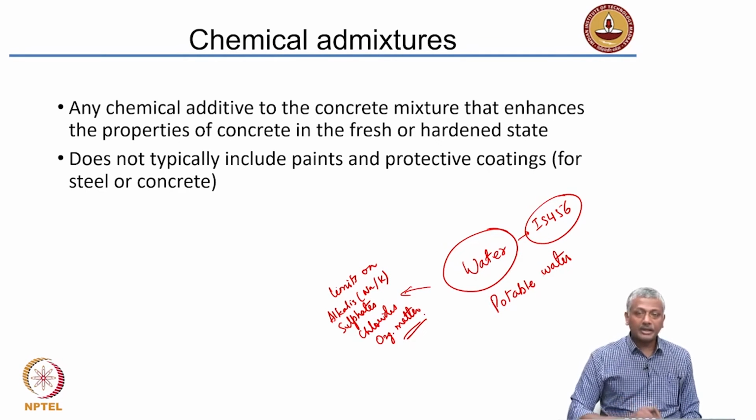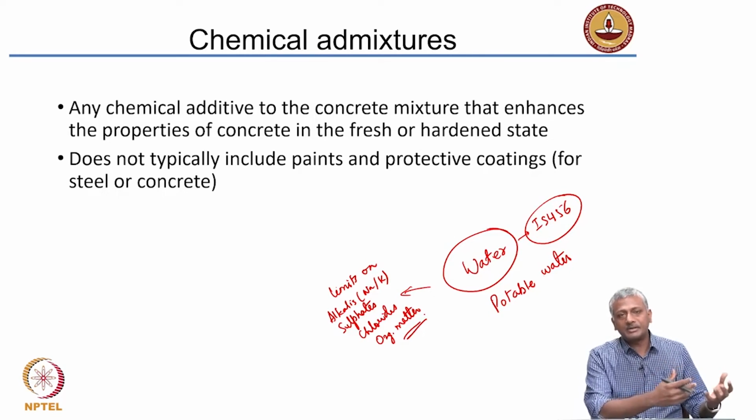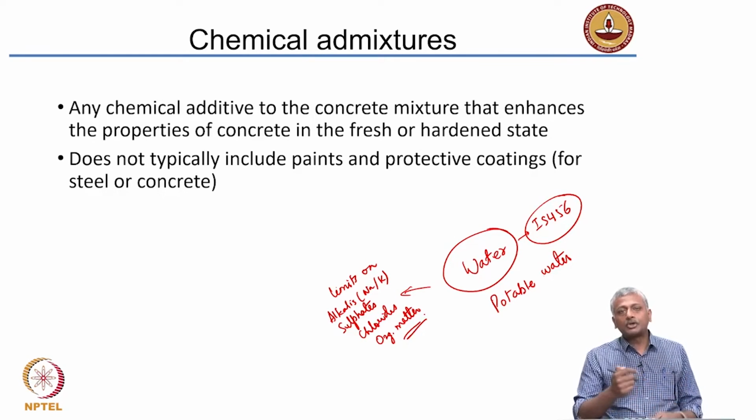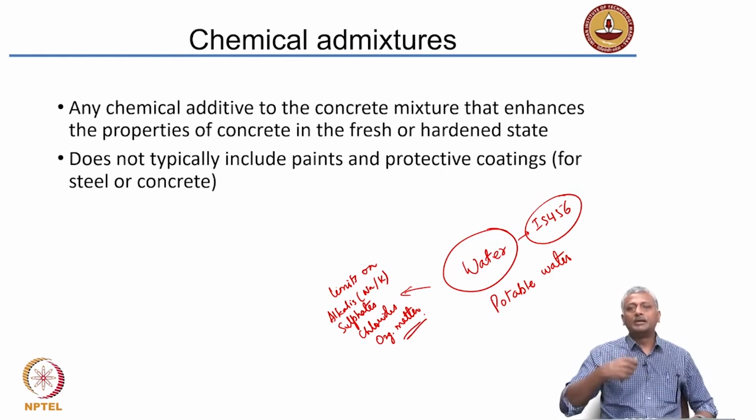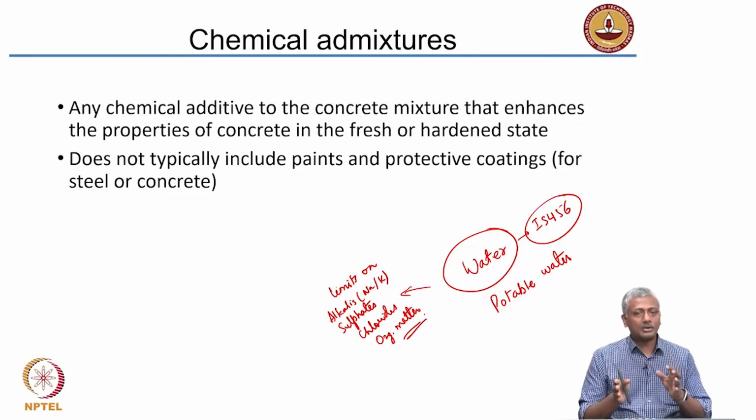So, water obviously you need to pay a lot of attention to, because not only is water used for mixing the cement and aggregate together and also reacting with the cement, the water later is also used for curing the concrete. After the concrete has been formed and you remove the formwork, you start pouring water on the surface. That is called curing. And that is a very important process. So, a lot of water is required in concrete construction for mixing inside the concrete as well as for curing.